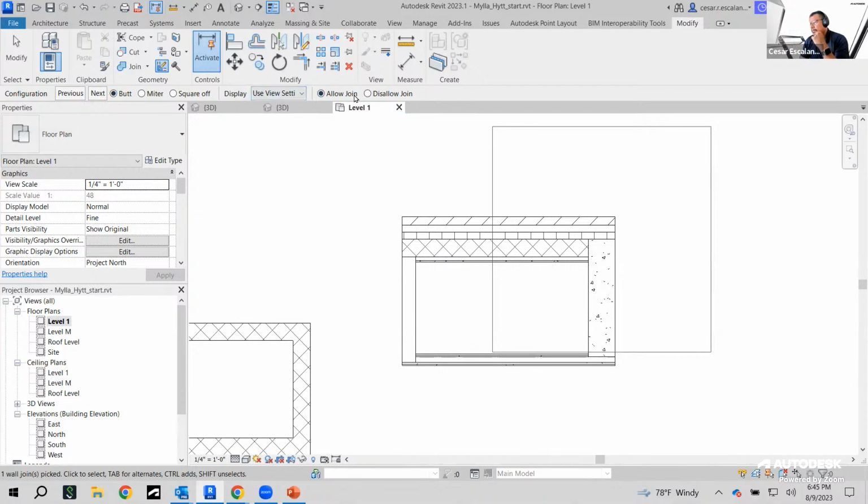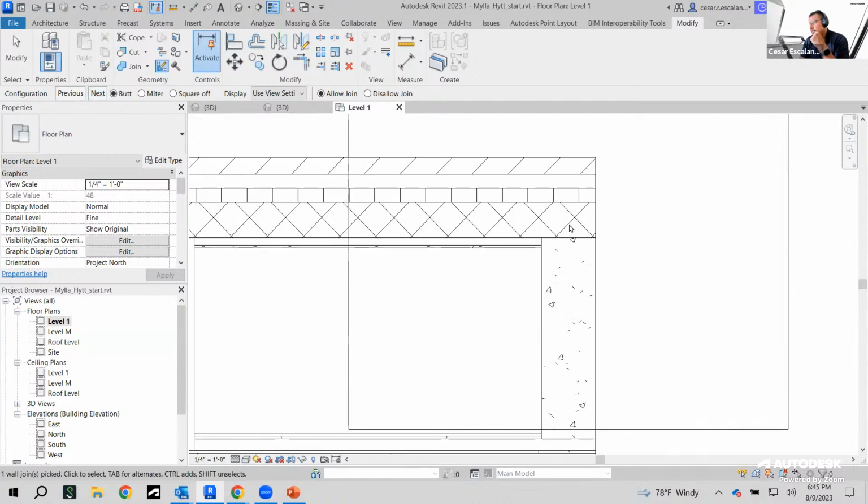And then when you hit this next button, you see how Revit starts changing the weight or the priority of the connection. So Revit knows that these two walls share the same, are abutting the core, but there are two ways to abut the core. Either this abuts to this one, or this abuts the other one. And so the wall joint helps you override how the layers connect to each other.